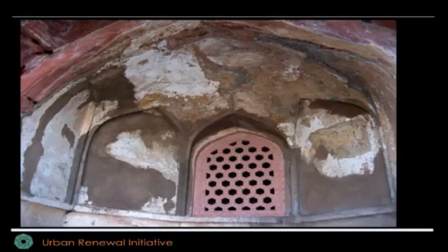Now, I want you to, for a moment, forget the cement. Just don't look at the cement, but look at what's happening around it. Look at the stone and the deterioration the stone is suffering. This is because cement is so hard that the water is actually coming, and this is structural stone. This is a true arch. This is not cladding. This cannot be touched unless I bring down the whole building. So the cement is not to be removed because it's ugly. It's not an aesthetic argument as some of our critics have made it out to be. It is a need for the preservation of the monument because the stone is just deteriorating.